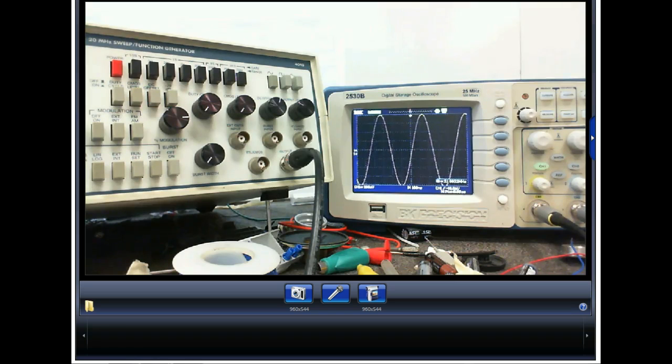And that's usually what happens: one of your outputs will blow and you'll lose your negative power supply. Your positive power supply is still there and your amp chips off. People keep resetting it and they burn their speakers up because they keep putting DC on them. So if your amplifier kicks its safety and you reset it and it kicks it again, don't keep doing it or you'll burn up those big expensive speakers. We got an amp in here, by the way. I need to show y'all if I can find it. It's a Lansing that is flat burned up.